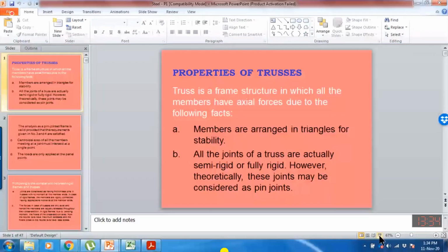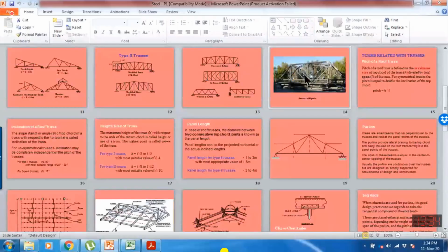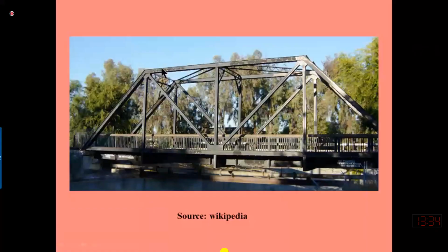Okay, from this drawing sheet, I need to explain the purlin. For example, we have this one truss and one truss on the other end. So this beam is a purlin, this one. Now this purlin is also a truss, a smart truss. But actually a purlin is a beam which connects the panel points of two trusses. So the length of this purlin is equal to the spacing of the trusses.